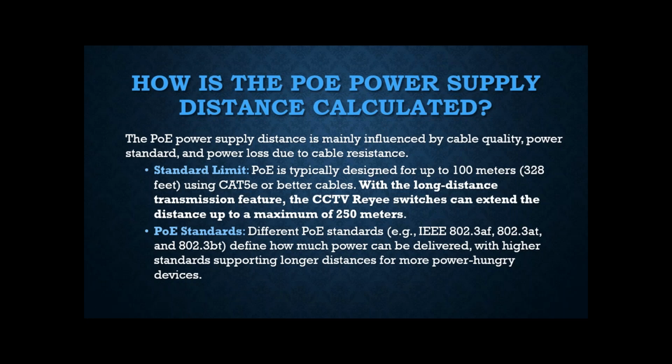And how is the PoE power supply distance calculated? The PoE power supply distance is mainly influenced by cable quality, power standard, and power loss due to cable resistance, so we have to take this into consideration. The standard limit for PoE is typically designed for 100 meters or 328 feet using Category 5e or better cables.